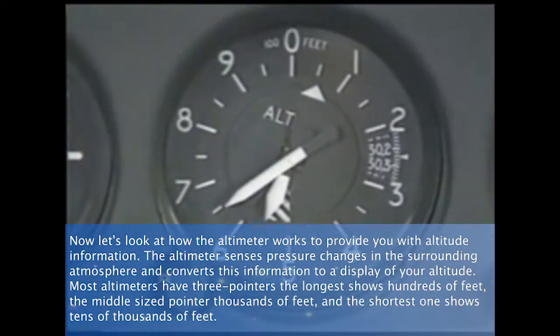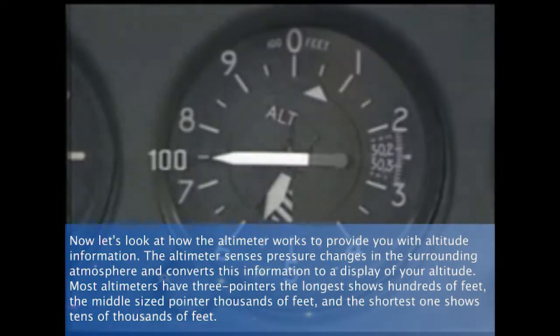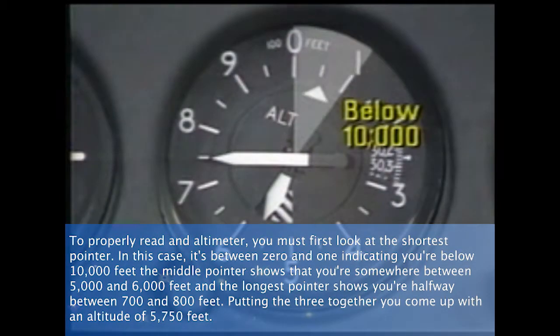The altimeter senses pressure changes in the surrounding atmosphere and converts this information to a display of your altitude. Most altimeters have 3 pointers. The longest shows hundreds of feet, the middle-sized pointer, thousands of feet, and the shortest one shows tens of thousands of feet. To properly read an altimeter, you must first look at the shortest pointer. In this case, it's between 0 and 1, indicating you're below 10,000 feet.